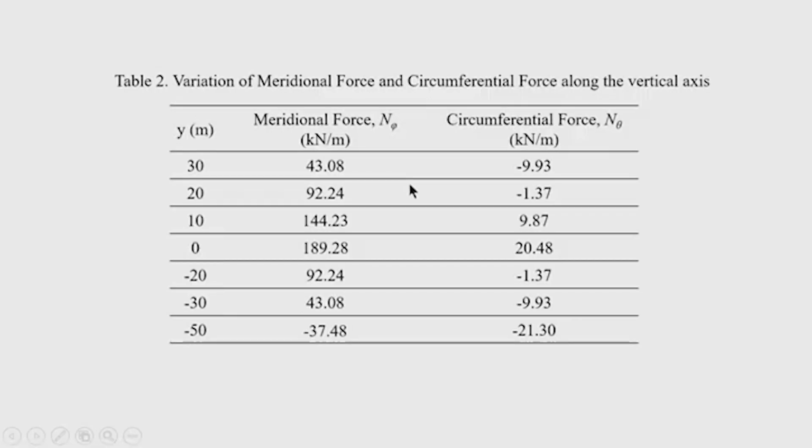That is found based on the area of steel that we have calculated depending on the maximum tensile stress found in this table. The maximum tensile stress found in the table is very low, as you are seeing here, and therefore the requirement of reinforcement will also be low.